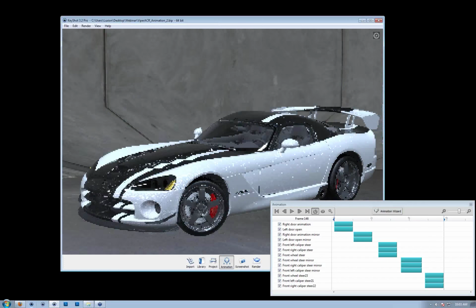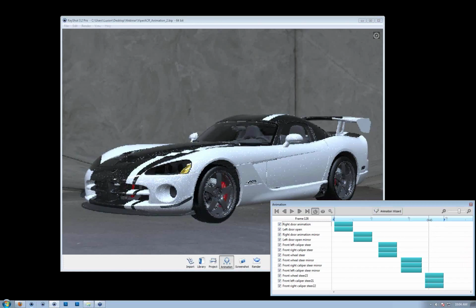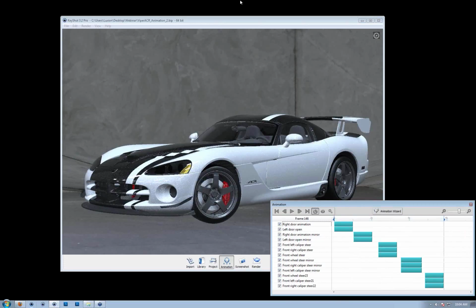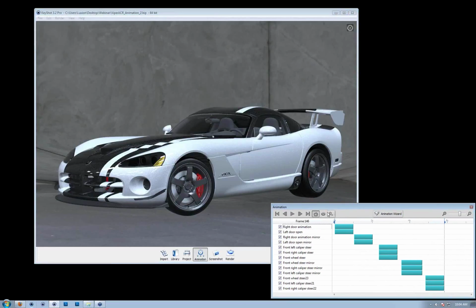A lot of the times when you're doing a car rendering, you don't want the wheels to be perfectly straight. So the animation system is actually a good way to turn things, and you can always fine-tune the positioning of those turned wheels just by scrolling through the animation. So my point here is the animation actually doesn't have to be used entirely for animation. You can use it to move things, which of course you have the move tool as well, but I will show some reasons why the animation system can actually be a little more helpful than the move tool.